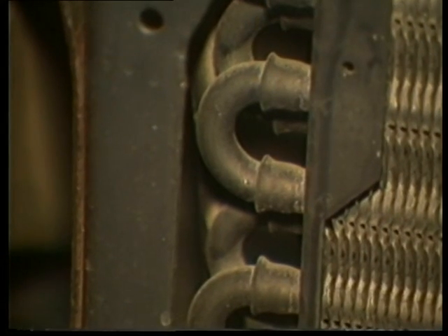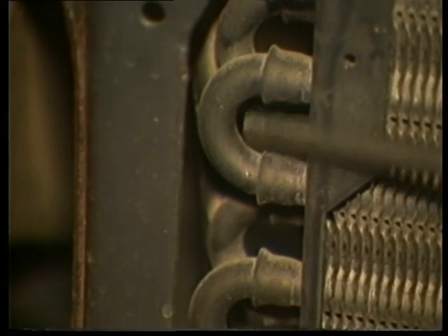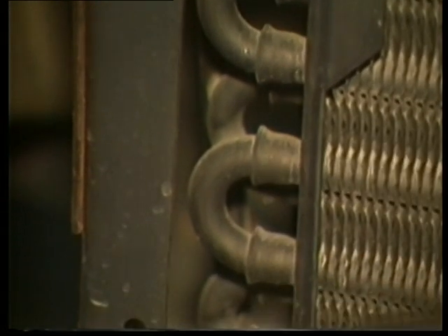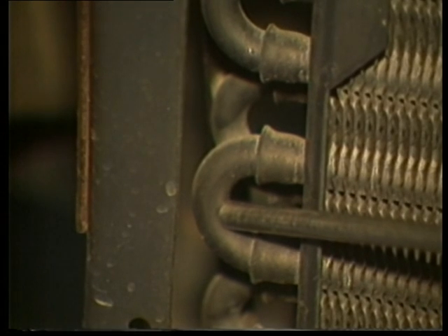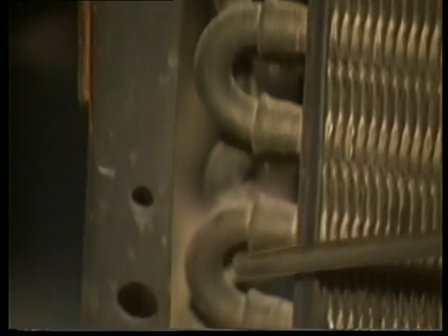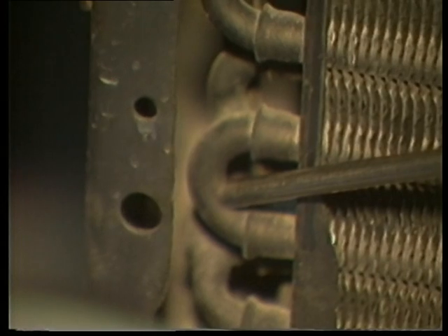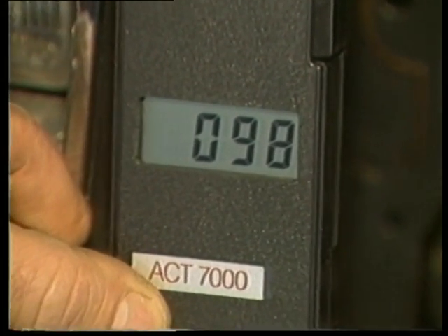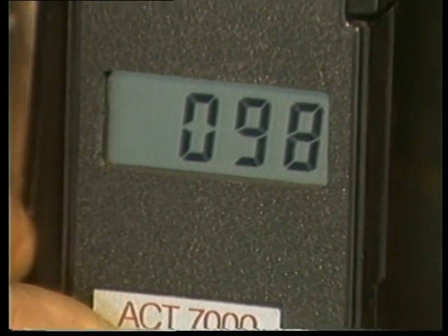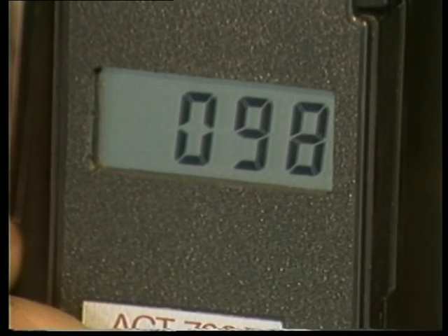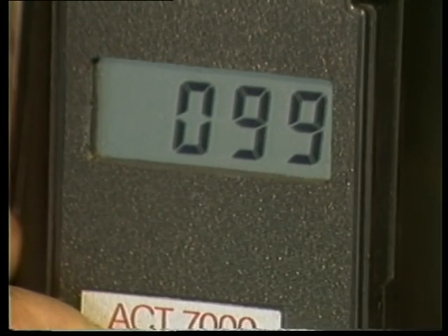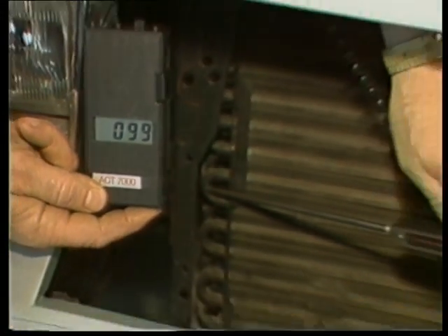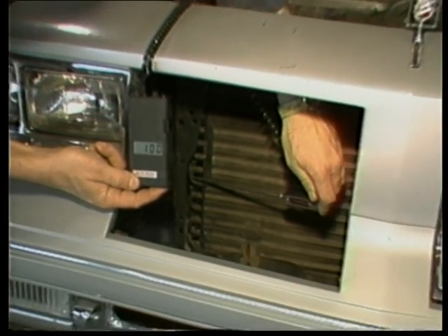Using a digital pyrometer to check the temperature of the condenser can find an internal condenser restriction. Generally, the temperature of the condenser should be uniform and only change a few degrees from top to bottom. If you find a sudden temperature drop at one location in the condenser, you have found a restriction inside the condenser tubes. The restriction can act as an orifice tube to cause a pressure drop in the refrigerant with an accompanying temperature drop.